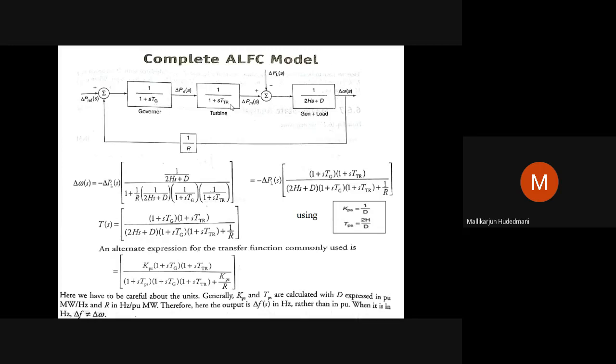Therefore, each transfer function block has its input and output values respectively. Like the governor has a reference point as its set point. Again, we'll see what this feedback is very soon. This needs a stimulus called the reference point, the set value within which it will work. If the set point is to be changed, this will come into the picture. So this governor will transform the requested power displacements into physical displacement of the valve by its transfer function, called the first order lag function.